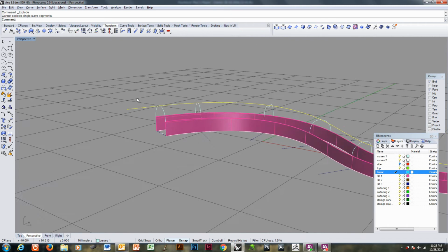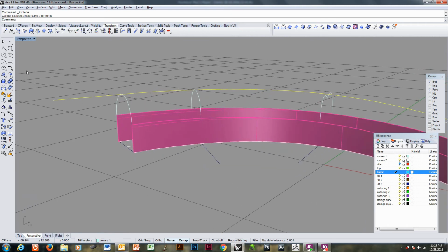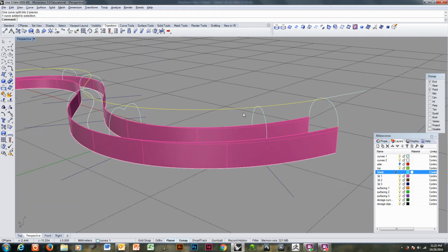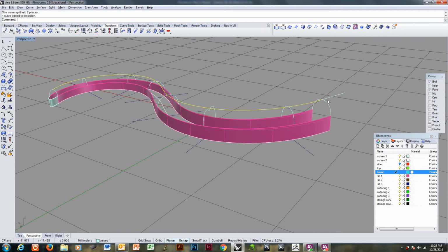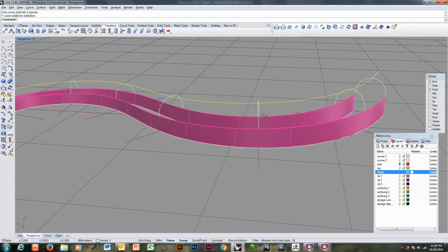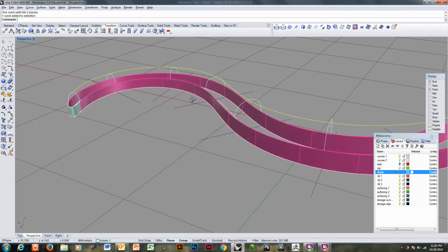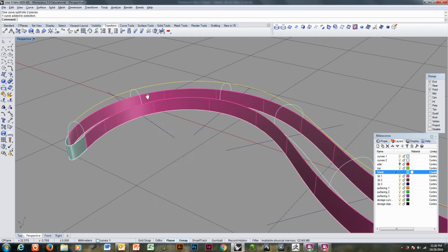Oh, it's a single segment now, so I'm going to have to split it. I will split it with this section. There we go. What I want to do, class, is draw a curve that extends by arc to point to this low point, and then extends by arc to point, actually a blend curve to where I want it to go smooth again. I want it to go smooth here.